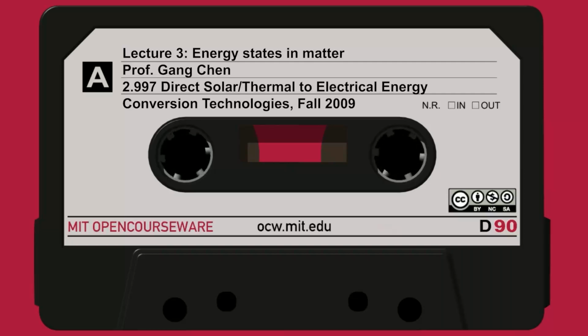Now silicon, that gap is about 1.12 electron volts at room temperature. So silicon becomes a semiconductor because this gap is not very large. And if you cool silicon to 0 Kelvin, it should be an insulator, because there's not enough thermal energy to move the electron from here to here.